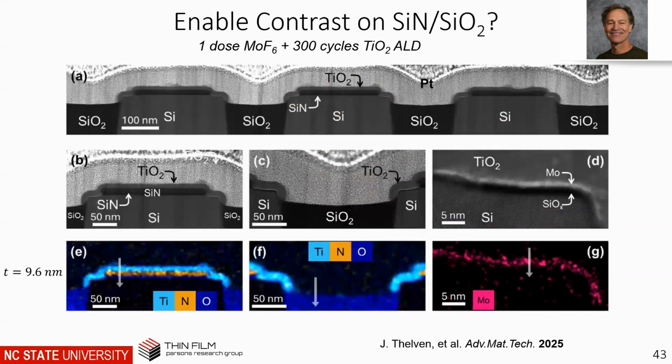And it turns out it works. So what happens is we are able to deposit on the silicon nitride and get no deposition on the silicon oxide. So that fluorination step fluorinated the oxide, and so it couldn't react. And so it didn't fluorinate the nitride, right? Obviously, it didn't fluorinate because it reacts. Is that true or false?